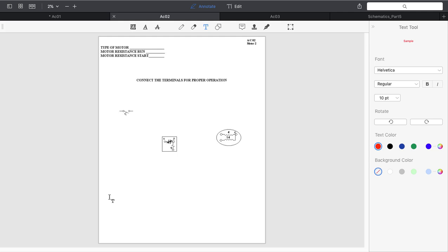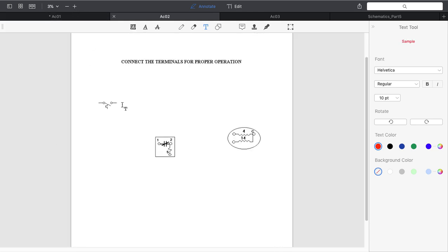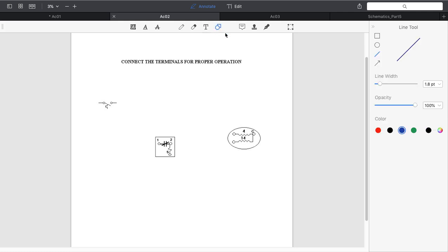So what we're going to do is we're going to go ahead and wire this in, the same way as we did in the last one. So I'm going to come out of here. I'm going to go ahead and give it my line because I don't like skipping that. I'm going to come out of here to pin 1, because we always power potential relays with pin 1.